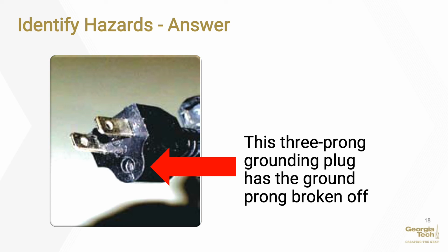Equipment grounding only works when there is a permanent and continuous electrical connection between the metal shell of a tool and the earth. If a wiring defect in the tool allows an energized wire to touch the tool's metal shell, grounding provides a low resistance path to earth for the resulting current. This will generally allow enough current to flow so that a fuse will blow or a circuit breaker is tripped, thus turning off the electricity in that circuit. If this grounding path is broken at any point, the tool is not grounded and the operator is at risk